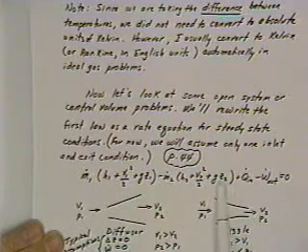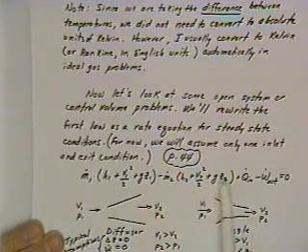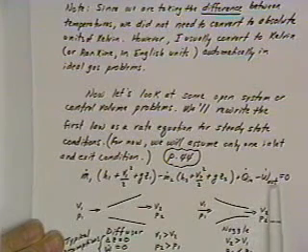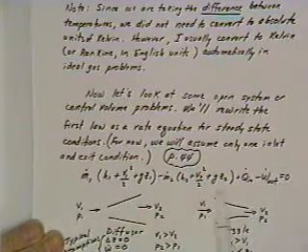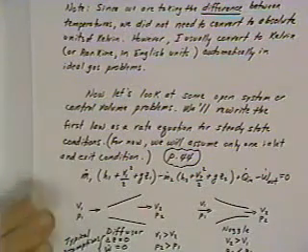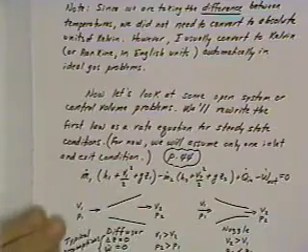That's the exiting enthalpy, kinetic energy, and potential energy term, plus Q dot in minus W dot out equals 0. So this is our basic equation for the first law, written as a rate equation for steady state conditions when we have only one inlet and one exit condition.